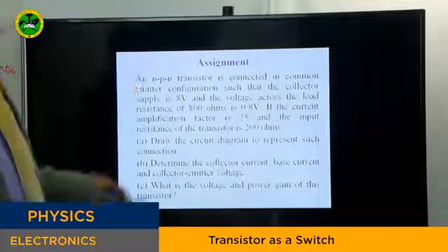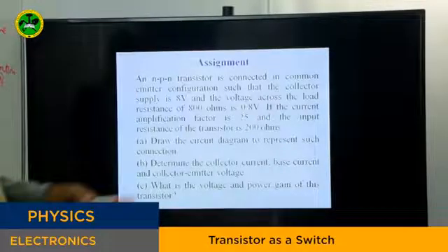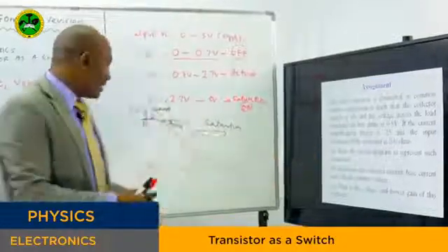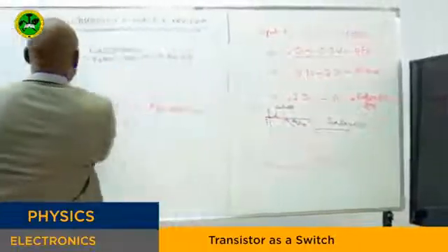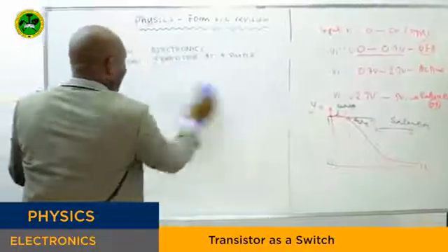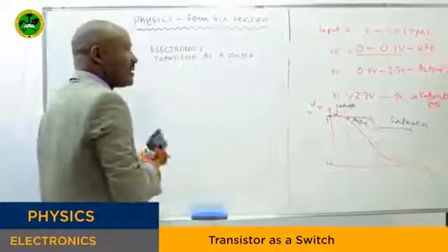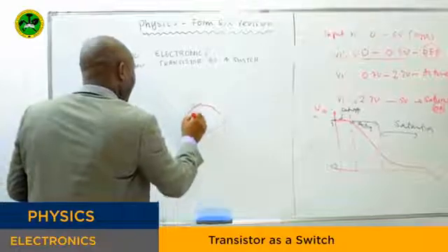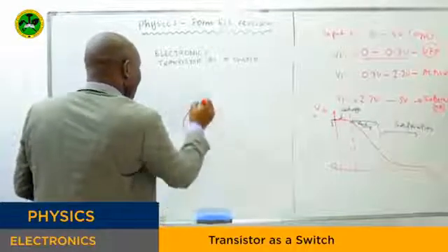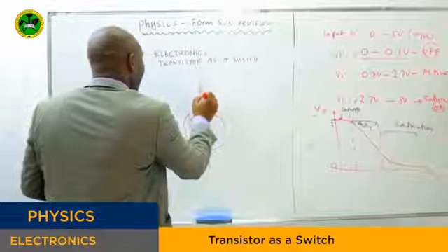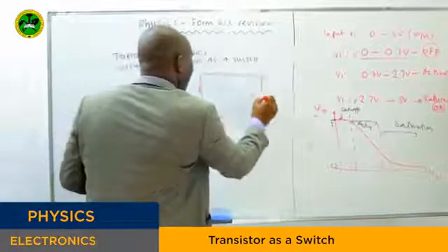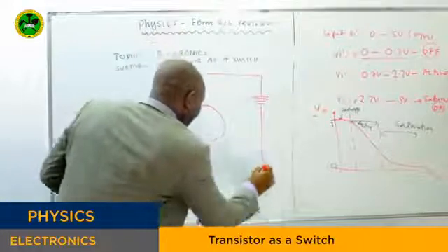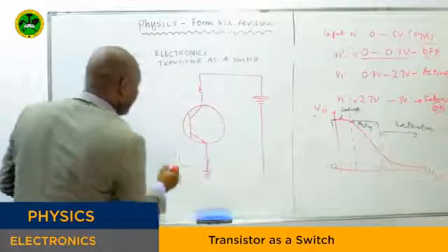This is the last part of our discussion. So I think you can do that. Step number 1, you're supposed to draw the circuit diagram, and maybe to show the starting point, you draw the circuit in the common emitter. This was the common emitter arrangement. This was the supply voltage, which is given here. This terminal should be connected to the ground.